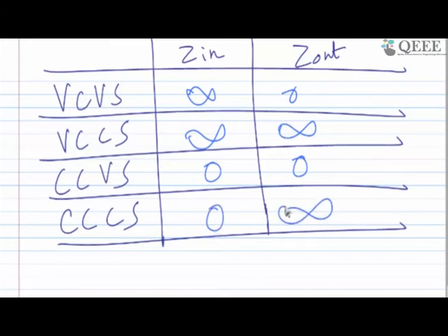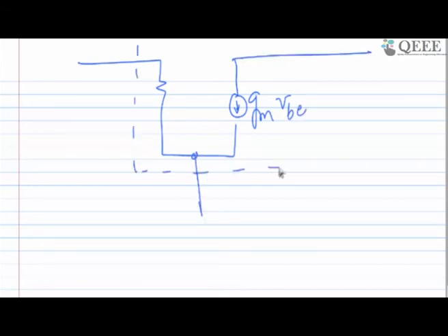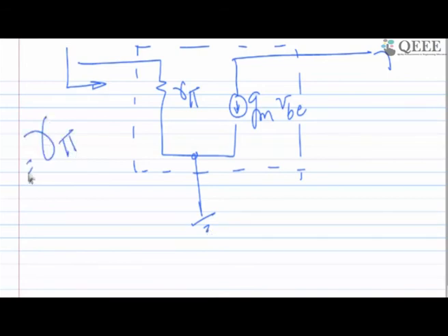So if it follows this condition, then for our case, when we started, our circuit's input impedance was infinity and output impedance was 0. So that circuit was a voltage control voltage source. However, for a BJT, whose small signal model looks like this one, if I see from the input side, by connecting everything else to ground, I am going to see R pi at the input side.